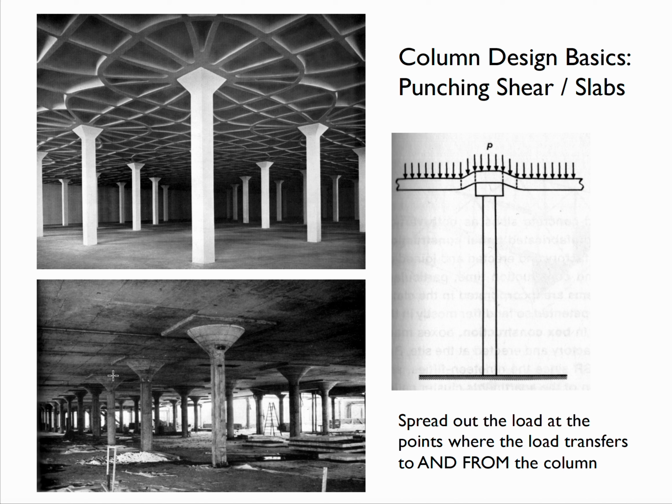A couple other design basics. We talked about this in the lecture of the shear, but the idea of punching shear. So when all those forces were accumulating in and around a column as they're going to transfer from the slab downward, again, we have a concentration of forces. Whenever we have a concentration of forces, we want to add more mass.